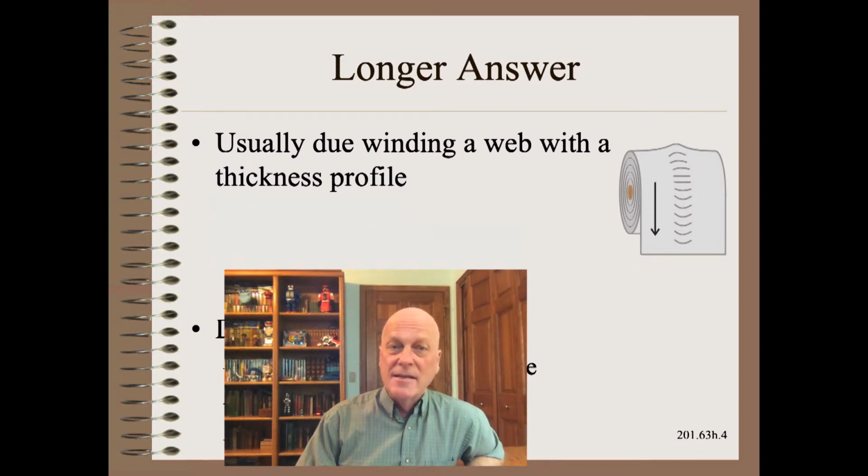In most cases, the web is not formed baggy. Rather, the former or converting operation is making a material that has no bagginess, but does have a thickness-related profile variation. When this material is wound, material is permanently stretched in the thicker lanes. This is the mechanics for almost every case in film and foils. While other materials such as paper and textiles can be formed baggy, they also commonly suffer from this thickness profile variation mechanism.